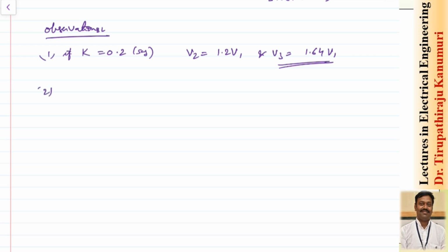The second observation is that the value of K is equal to C1 divided by C. As the value of K is increased, the string efficiency automatically goes on falling down. So, more non-uniform distribution will be there. This is the second observation.